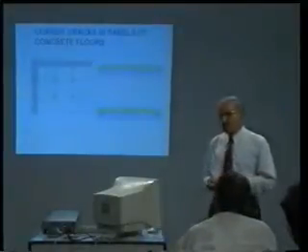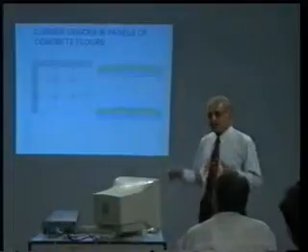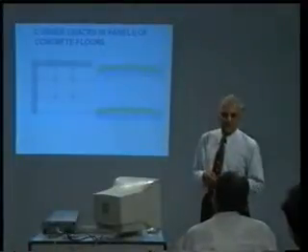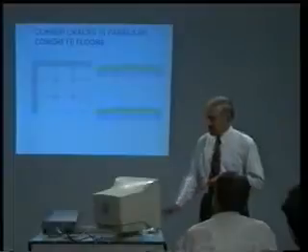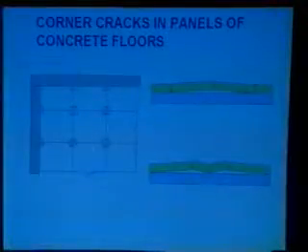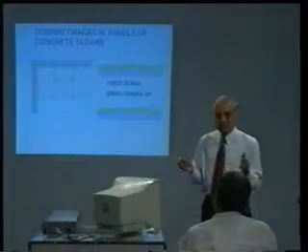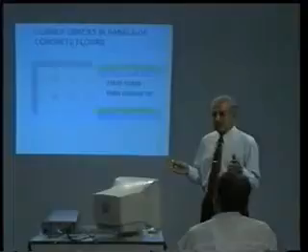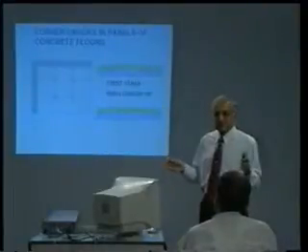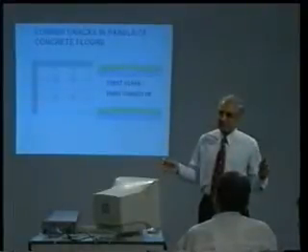Now, there is another problem related to large floor panels, particularly in factory and industrial buildings. You have cracked up portions at the corners. Now, how do these cracks occur? In the first stage, during the expansion of the floor slabs, the movement of the floor slabs is restrained at the corners, and they are made to move inwards.